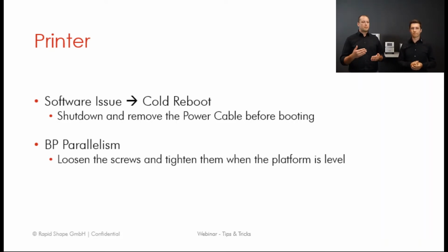It's about that process that you have to know what to check for, because when you tighten one corner, it does have an effect on the other corners. And at some point, if you turn too much and go down the rabbit hole too far, you end up with a warped plate, and then it's very confusing to go back steps. So just resetting it in this sense would make the process a little bit easier, I believe.